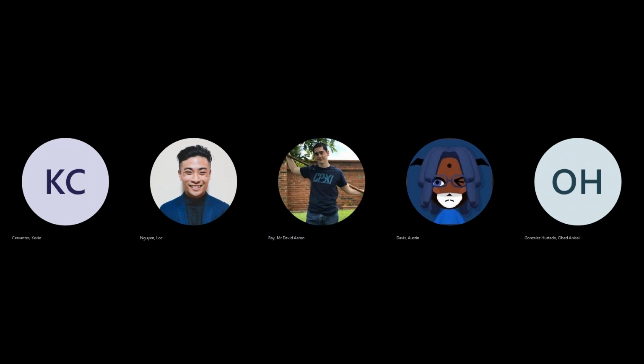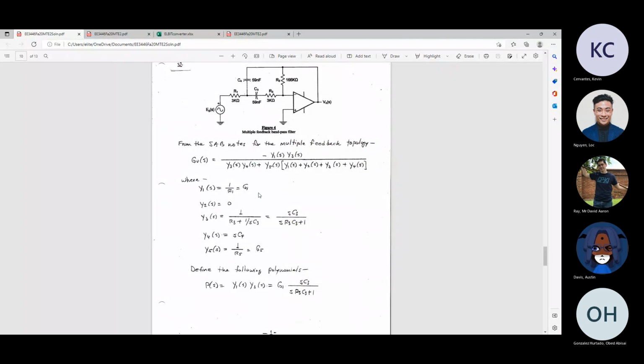There we go. Okay, you see this? Yes. So you're going to have these notes from SAB notes for multiple feedback topologies. And then it's going to give you some gain equation like this. And then you're going to have to determine what is your Y1, or what are your admittances for these values, and then you're going to plug that into your calculator. And then your calculator is going to give you, for this, I believe, a second order equation.